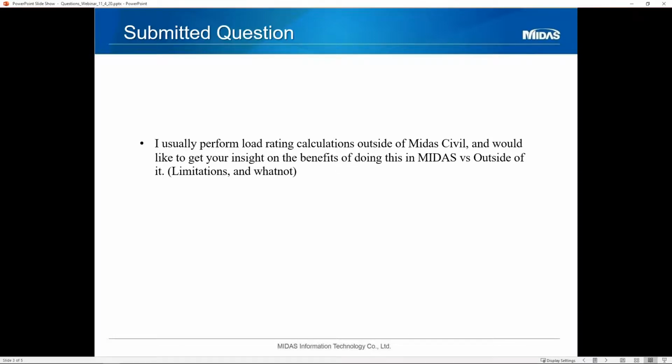really just getting with your controlling agency. So a lot of the DOTs use, say, AASHTOware as their primary load rating, not just rating software, but actual bridge management software. And that may be linked up to their bridge network so that when they want to run a permit vehicle through, they've got a set number and they can pull the files of each of the bridges it might be going over and run that all through AASHTOware.